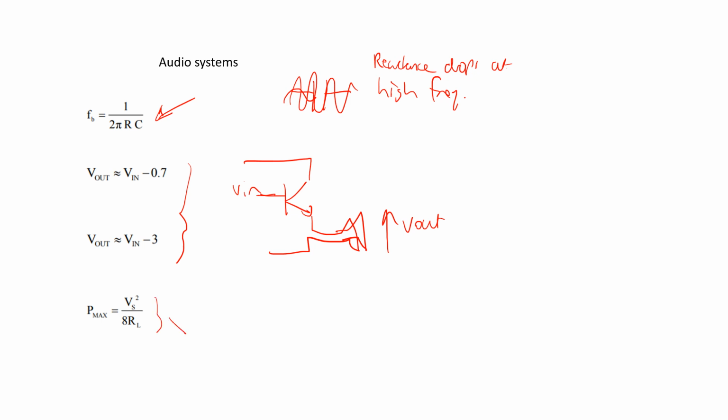And then this one is the power amp. It only works for the push-pull. Remember the push-pull? See if you can draw the push-pull using MOSFETs. Make sure you put the arrows on as well. So I'm going to do the easier one using transistors here to show you. This one will have crossover distortion.